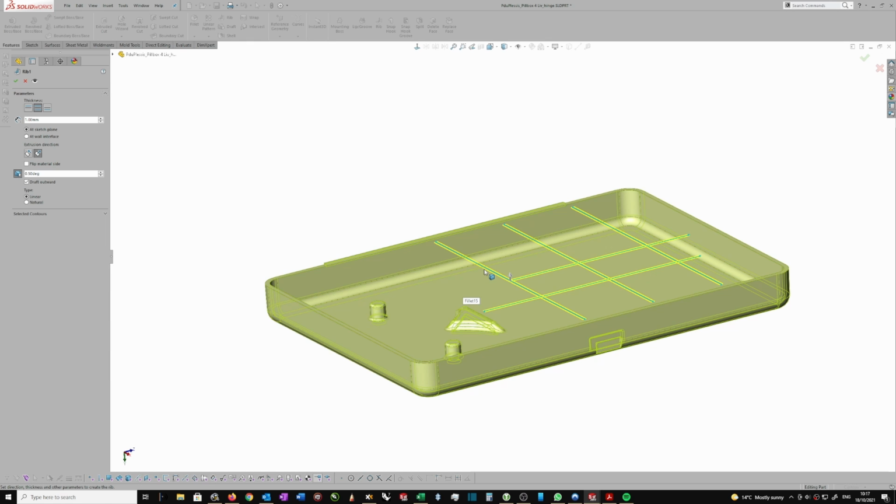Remember, it needs to be no more than 2/3 of the thickness of the wall that you've created the part in. So I think my wall thickness here is 1.2. A very simple way to do this is type in your wall thickness, use the star button, which is the equivalent of times, and then type in 0.6 or 0.66 or whatever it is that you want it to be, and it'll give you the figure, which is 60% or less. In this case, 60%. It'll do the calculation for you. You don't have to do anything else.